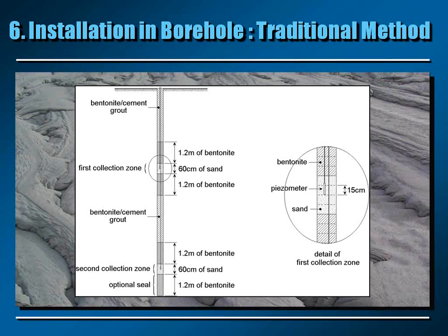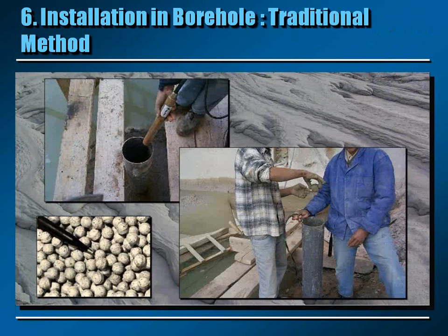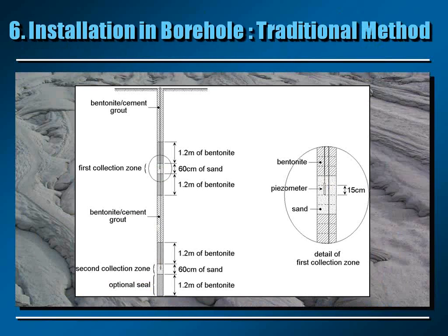And finally, the installation in a borehole. The installation in the borehole is more difficult. The traditional method consists, as I mentioned quickly earlier, of isolating the zone where the piezometer is installed. So you need to make a bentonite plug just above it and sometimes just below it. And this installation is not easy, because it is time consuming.